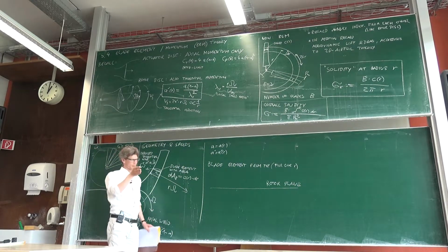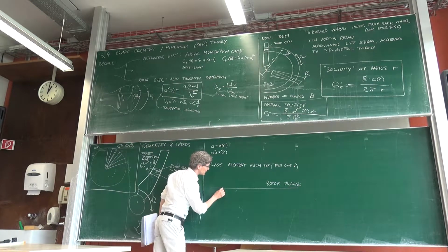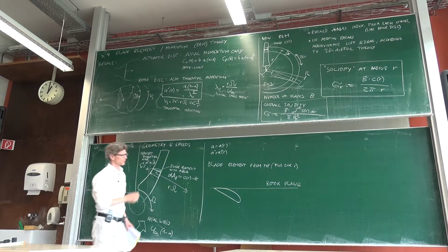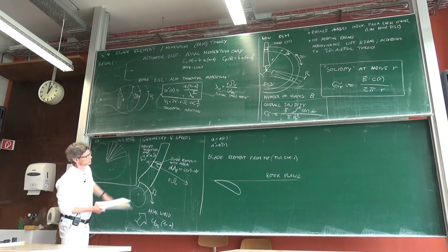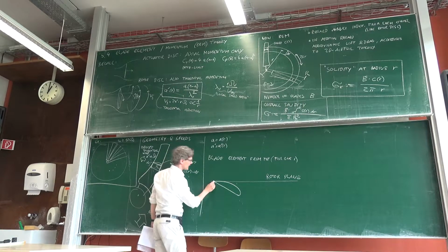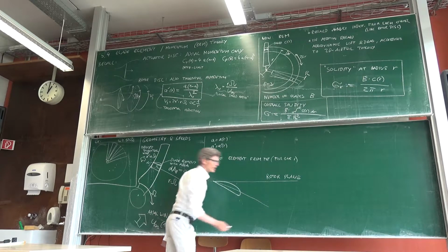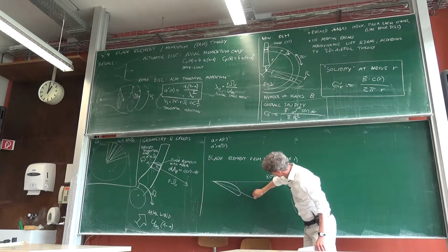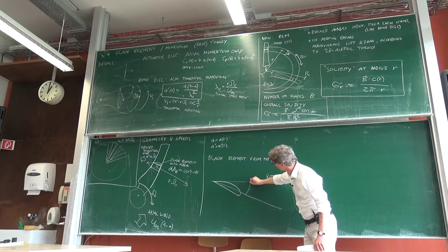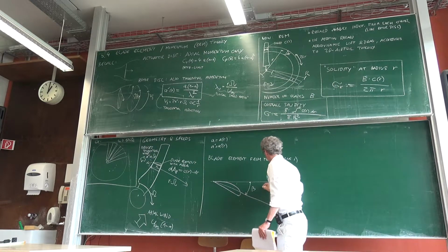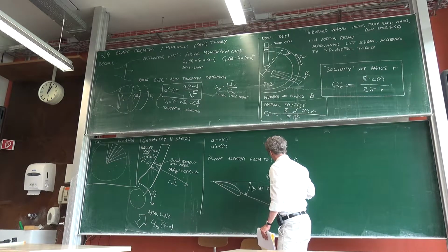The blade element, I mean, if you look from the top at this wind turbine, right? So then there will be a wing profile that could look like this. This wing profile will have some line which defines its geometric orientation. And this line is something that we can change with our pitch actuator if we want. But I will just assume it to be fixed. So we call this angle here beta. It's the set pitch angle, I mean, the pitch angle that we set.